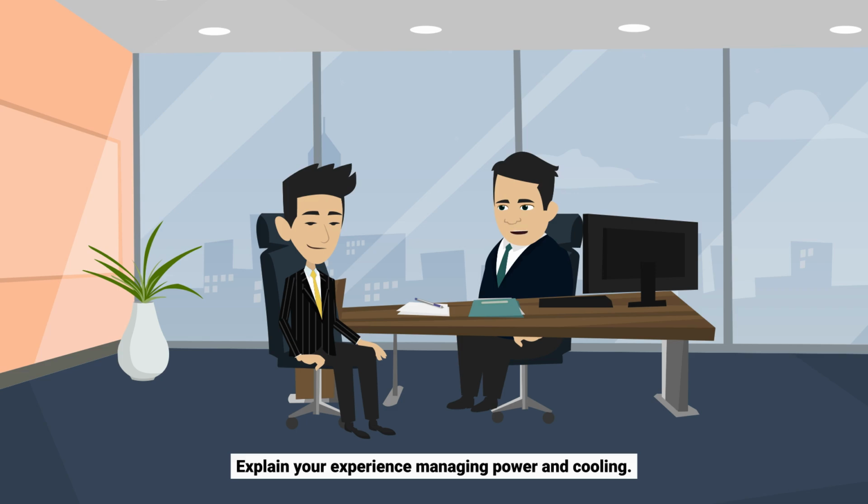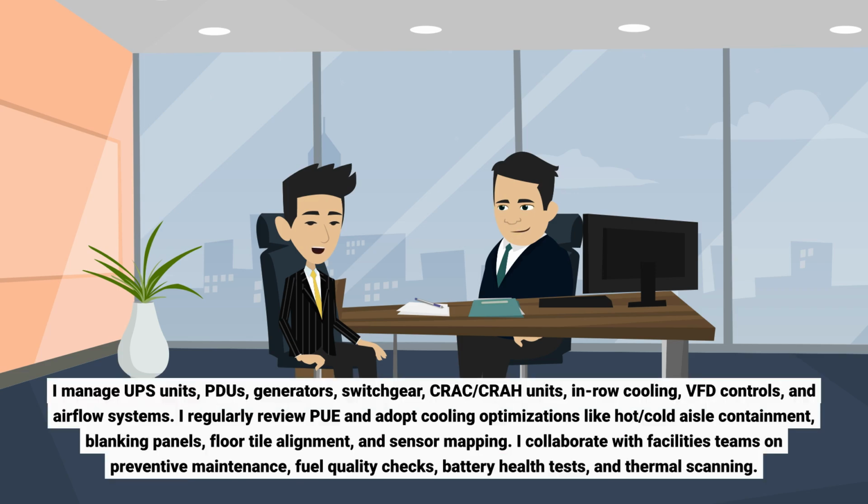Explain your experience managing power and cooling. I manage UPS units, PDUs, generators, switchgear, CRAC, CRAH units, in-row cooling, VFD controls, and airflow systems. I regularly review PUE and adopt cooling optimizations like hot/cold aisle containment, blanking panels, floor tile alignment, and sensor mapping. I collaborate with facilities teams on preventive maintenance, fuel quality checks, battery health tests, and thermal scanning.